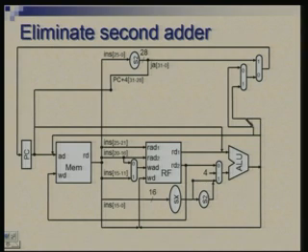So, at the moment I am keeping these two, both of which look identical right now, but one will come immediately from the output of ALU, one will come from a register which is following ALU. So, that distinction will show up later. At this point you just take it like this, that we are simply retaining them. If one was following this kind of design process, and you are not able to see that, you may eliminate one of these. But it does not matter, if you need a separate one later, then you can bring it back into the picture, but I am just following this approach.